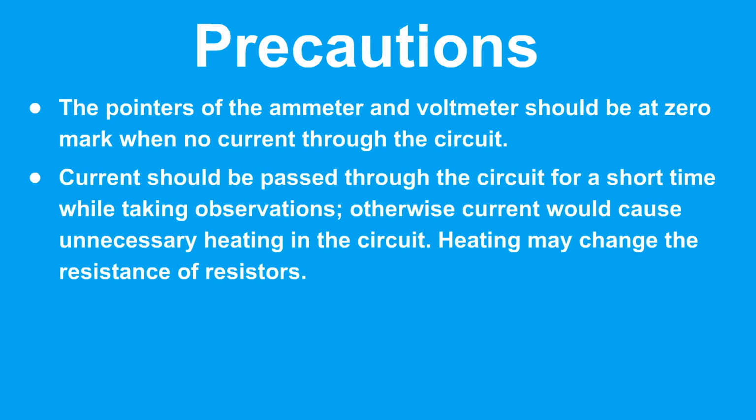Current should be passed through the circuit for a short time while taking observations. Otherwise, current would cause unnecessary heating in the circuit. Heating may change the resistance of resistors.